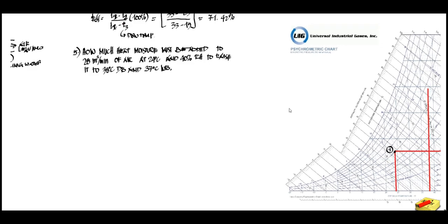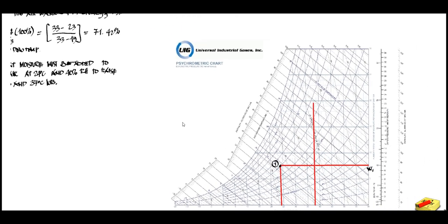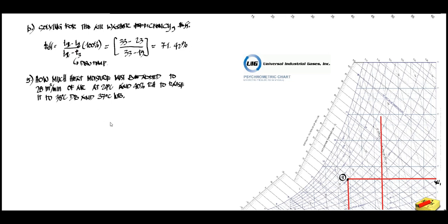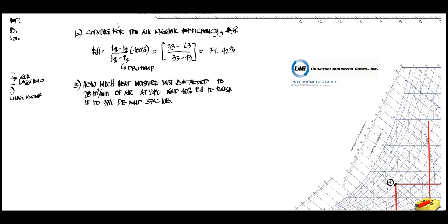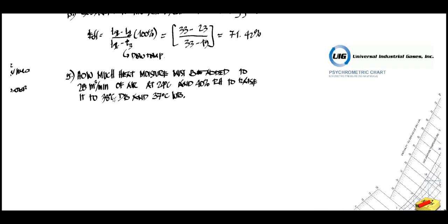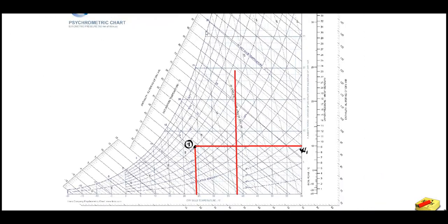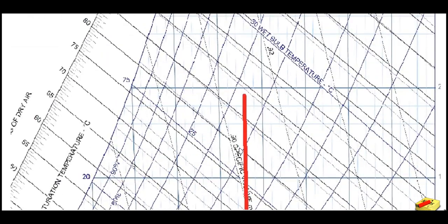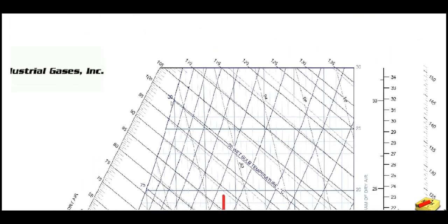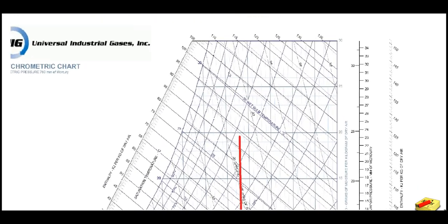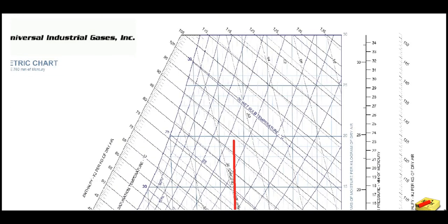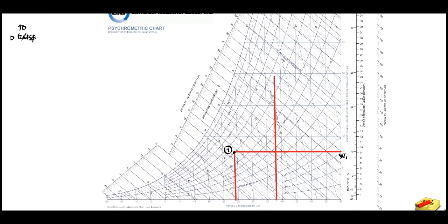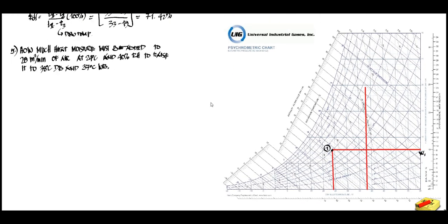So continuing, one of the problems we encounter here is that you will notice we have a temperature of 38 degrees Celsius and dry bulb is 37. If you look at the psychrometric chart that we have here, we have 20, 25 and 30, then 30, 31, 32, 33, 34, 35. So that is already beyond the psychrometric chart that we initially used.